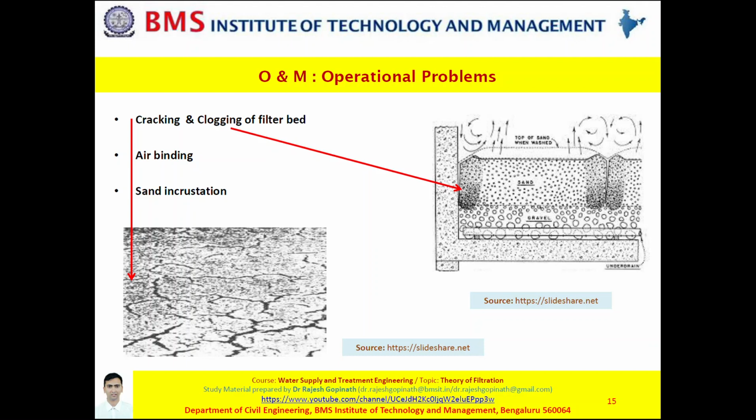During the process of filtration, there are releases of dissolved oxygen and certain other gases which eventually form bubbles, and these bubbles occupy those empty spaces or the void spaces in the filter media. Now when these effective spaces are occupied by these, the efficiency of the filter again reduces, leading to negative head, which is loss of head.